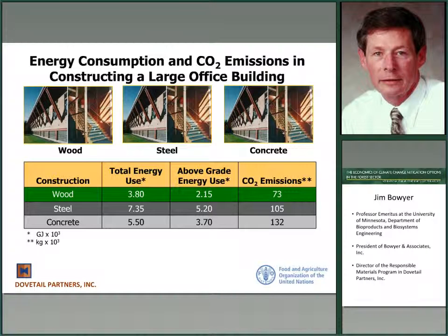And the reason for that, of course, is that when you take calcium carbonate, as shown here in the lower right, calcium carbonate is limestone. You put that in a lime kiln, heat it up to about 1700 to 2000 degrees. You convert calcium carbonate to lime, and you get carbon dioxide as an emission, a vast emission. And it doesn't really make any difference how energy efficient you are in that lime kiln. The basic chemistry of cement formation means you get vast quantities of CO2.